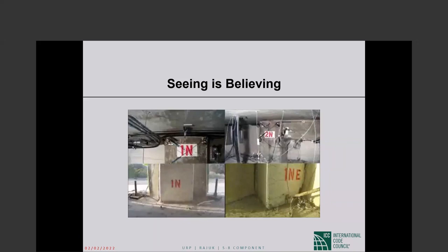And the basis of that is that the frames have much more inelastic deformation capacity than shear walls do. In wind design, we are not counting on inelastic deformations anyhow. So wind design is considerably simple that way.